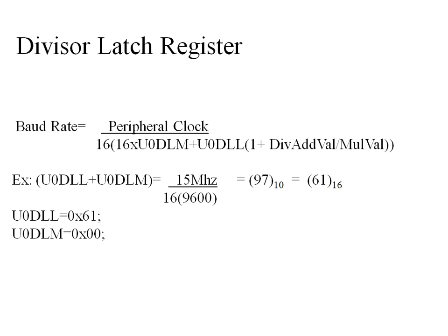If a value like 4 is set inside the VPB divider, then it divides the incoming clock, that is 60 megahertz, by 4, and the output will become 15 megahertz. Now this 15 megahertz will be given as an input to all the peripherals. So we can program that VPB divider value either to divide by 4, or to divide by 2, or to the same frequency as the processor is receiving.